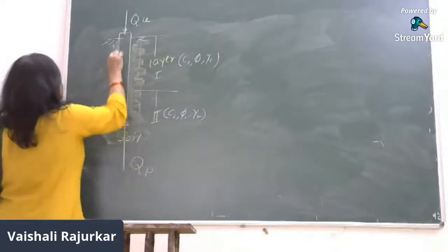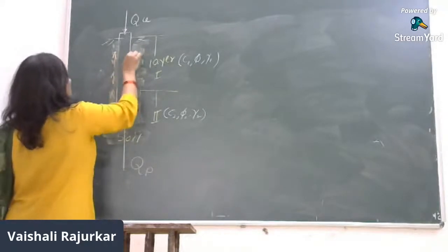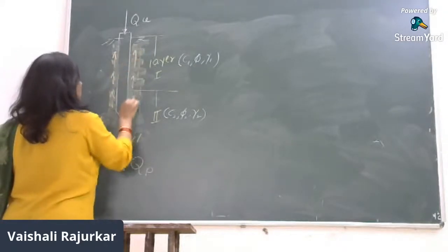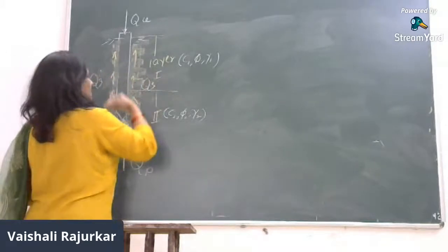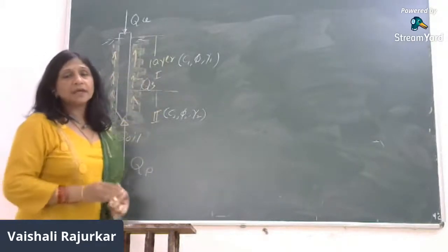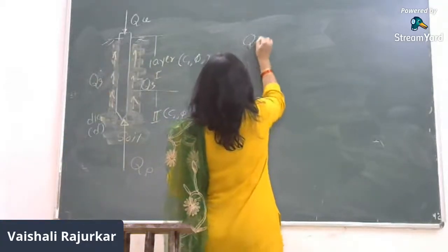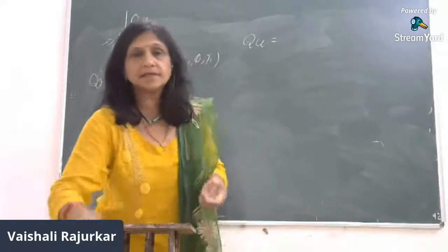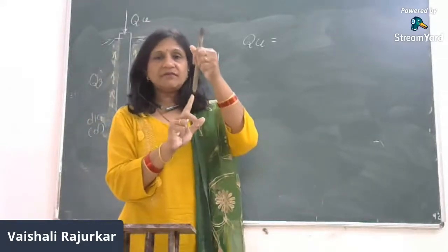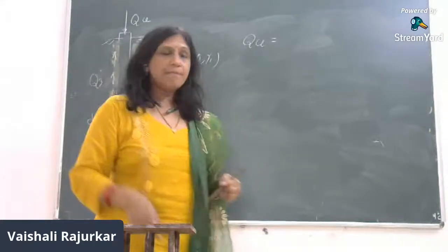That frictional resistance is acting over the whole periphery along the shaft, and this is called QS, that is the frictional resistance. So here we assume the ultimate load carrying capacity QU is equal to the tip resistance acting at the bottom and the frictional resistance acting over the periphery.